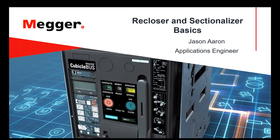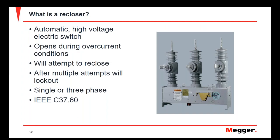So now that we've discussed some things about low voltage circuit breakers and primary injection, let's move on and talk about reclosers and sectionalizers. So what is a recloser? Well, a recloser is an automatic high voltage electric switch, and it has overcurrent sensing protection similar to a circuit breaker. However, whenever that overcurrent device operates and the recloser opens, it's going to attempt to close back in on the fault. The reason it does this is in an attempt to clear transient faults that may exist on the line.